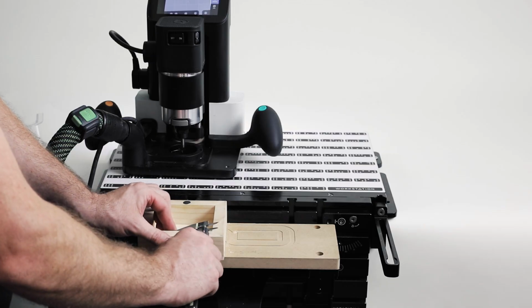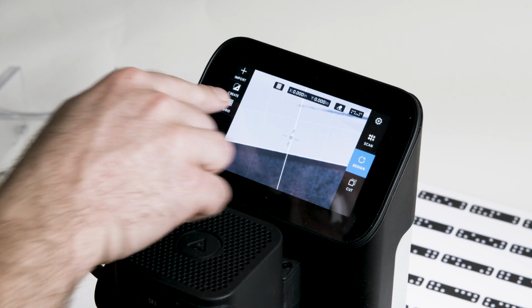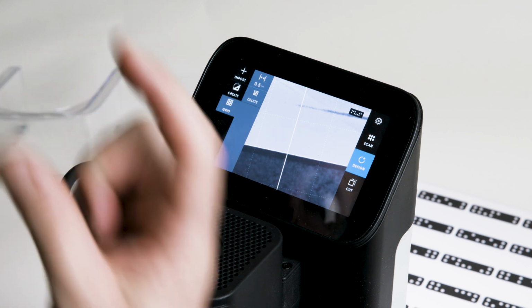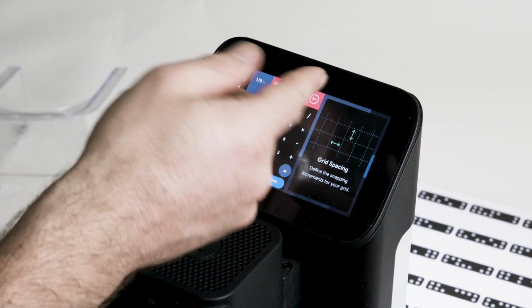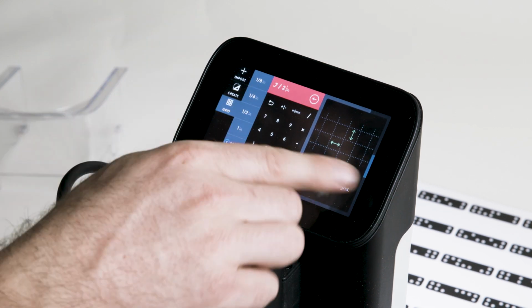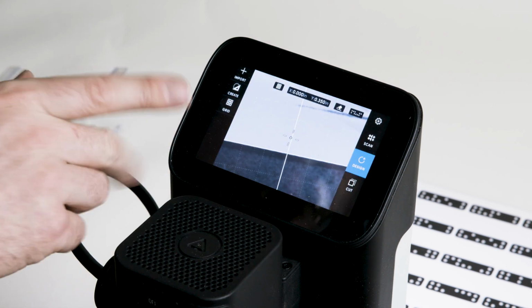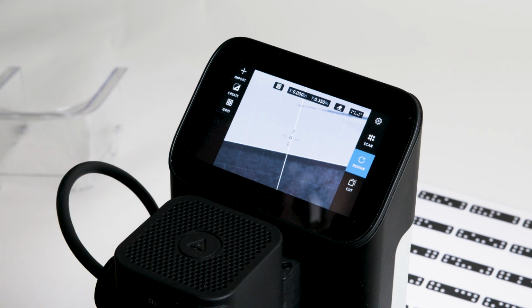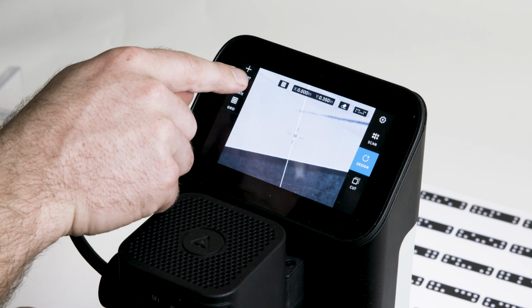Next step is we'll measure this to 0.7. So I'm going to center it in this stock. So to identify the center point of this stock, we're just going to let Origin help us out here. With grid modify, I can create an increment that is half that dimension. So in this case, it's 0.7, so it's actually easy math divided by 2. We could just enter it, but if it was some pretty complicated decimal, it's nice to be able to do this. So I just divided that by 2, which means the center point here is exactly centered in my stock.